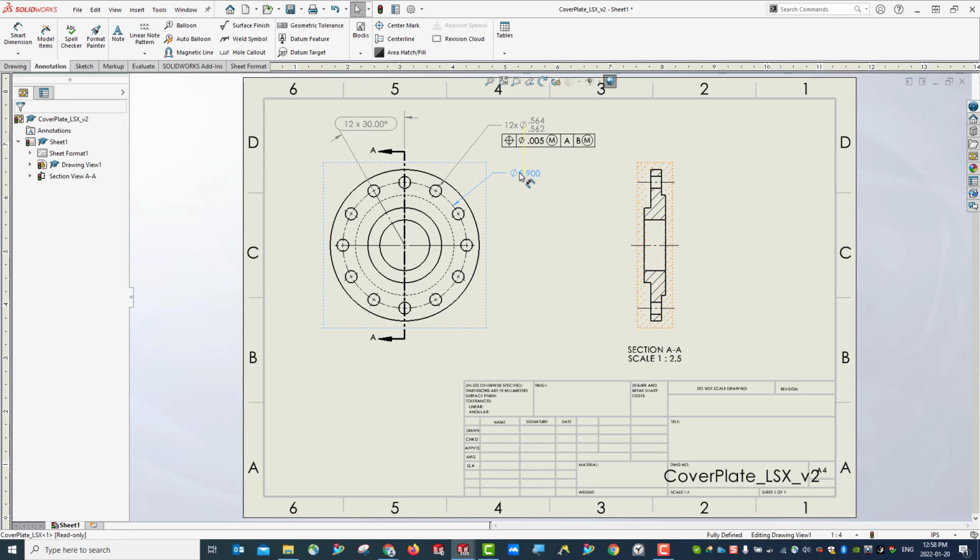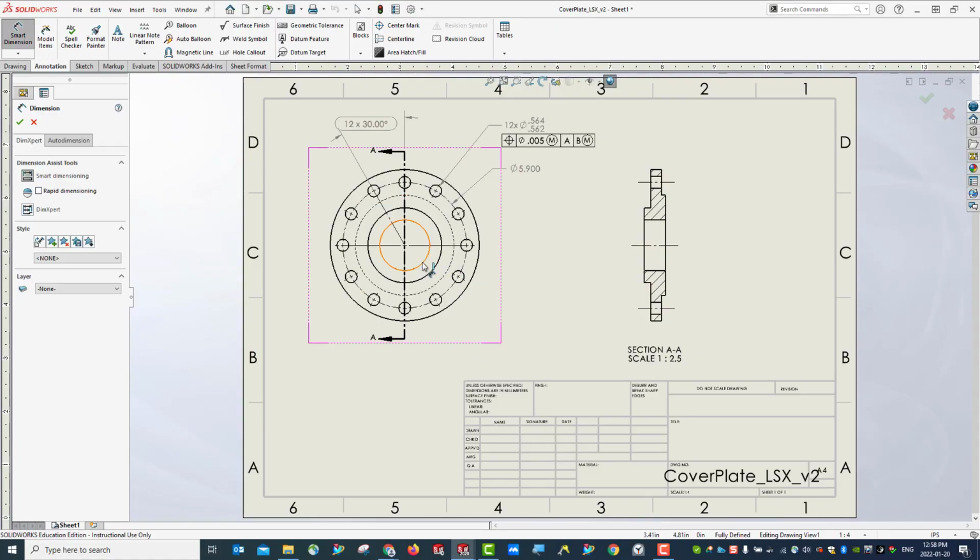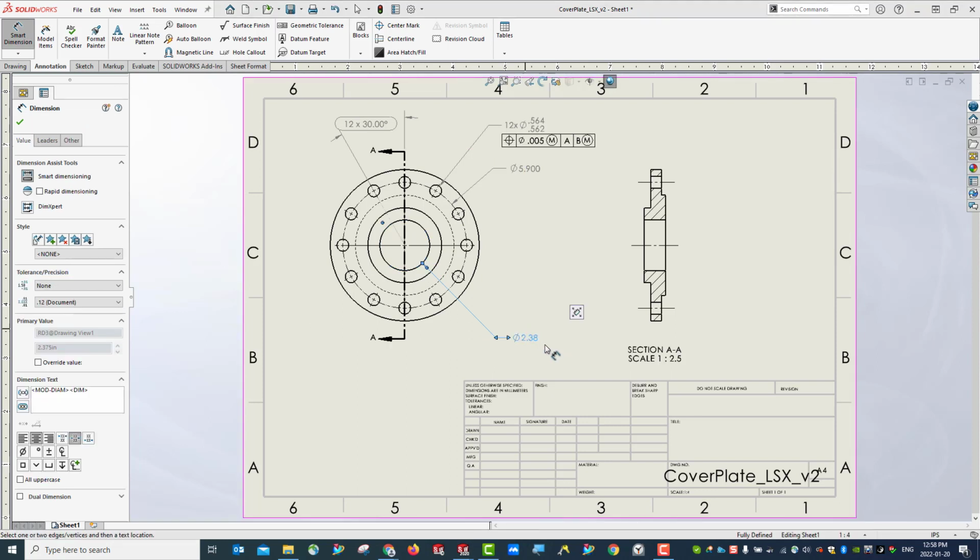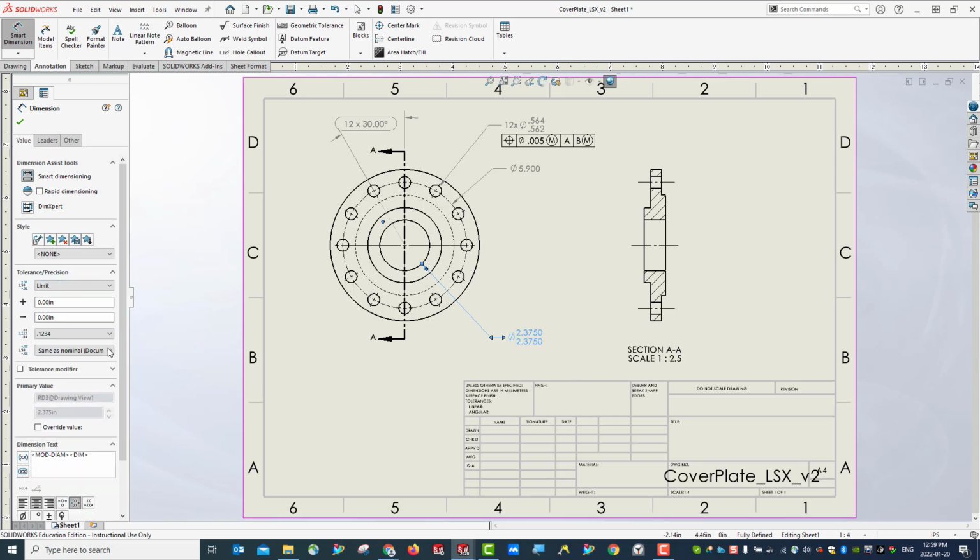Okay. You can make adjustment for its position. Save your file. Then we're going to create the dimension for this hole, center hole. Put it here. And you can see we have the dimension. The dimension has 4 decimal places, and also should have tolerance, and we use limit.